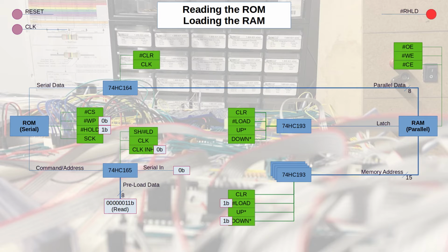Okay, as we move away from the trivial things and into the more detailed stuff, it's important to understand that this circuit is going to have 3 states that it can operate in. The first is in reset, meaning the voltage supervisor has detected a problem, or I am pressing the reset button and the circuit is actually in a reset state. That reset signal will be high, and that will happen independent of the clock. So anything that we do bringing it in or out of reset needs to be coordinated with the clock in